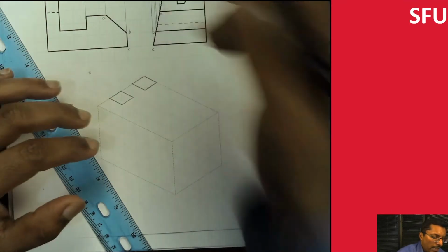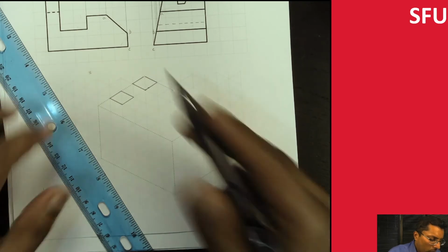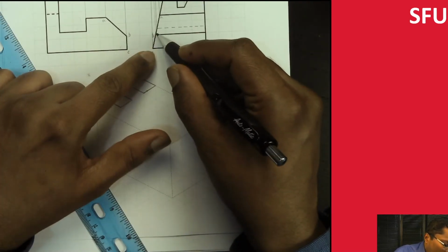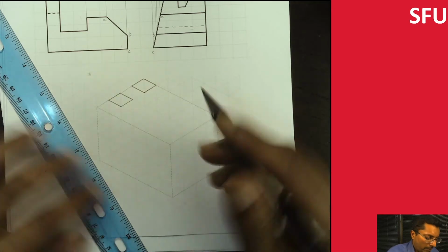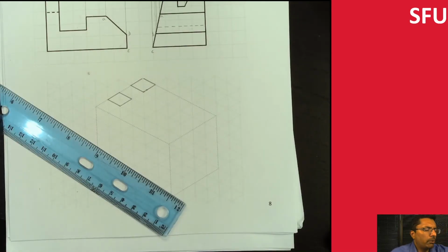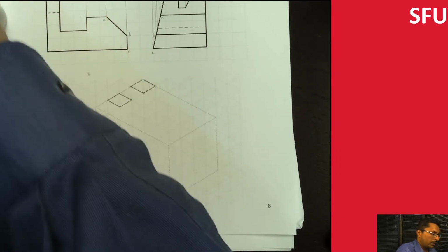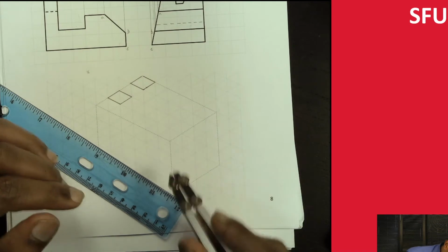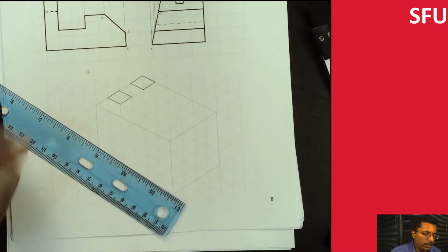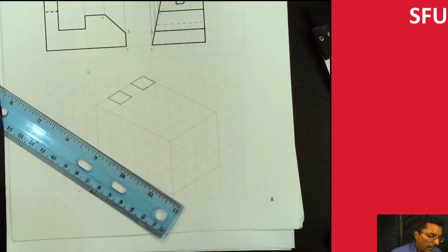So we go further and let's see what is actually located on the front plane. This is exactly on the front plane, so we can do that part. We just need to be a little bit careful that B is not exactly on the front plane; this is on the right plane. We need to transfer the distance. There are a couple of ways in which you can transfer the distance. One would be to measure it with the ruler. The other would be to use a compass. I'm going to use the compass from here to here, and then transfer this distance here directly. The other thing to note is you want to make sure you only travel along the X, Y, or Z coordinate, and you don't do a diagonal transition.